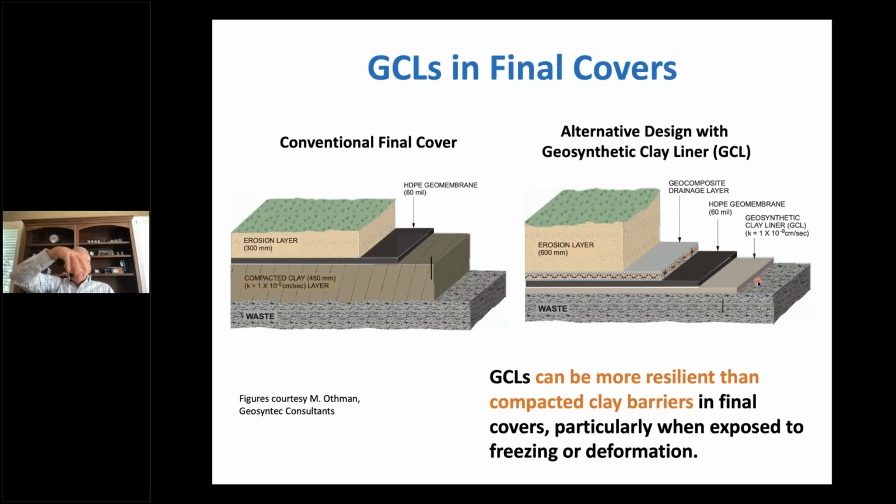And we'll also have water coming down from above. Our primary reason for having the barrier is to prevent infiltration, ultimately becoming percolation into the waste. But that water too will be very dilute. It will pick up salts as it migrates down through the overlying soil layers, but it will not have nearly the concentration that we would have in a lining system.